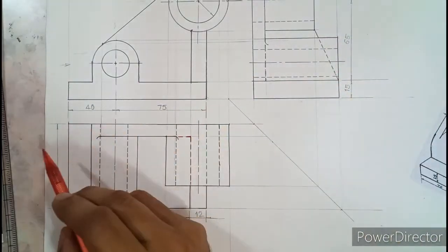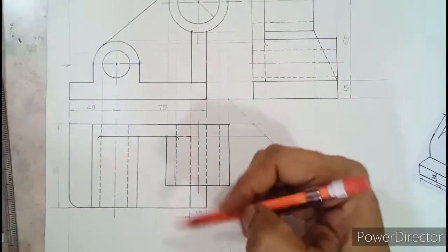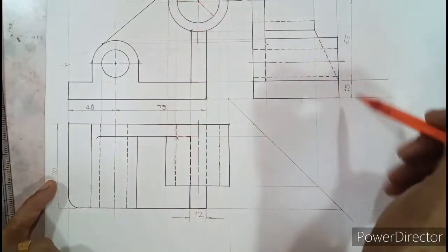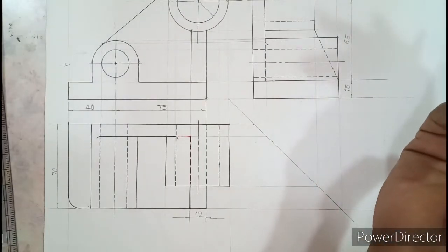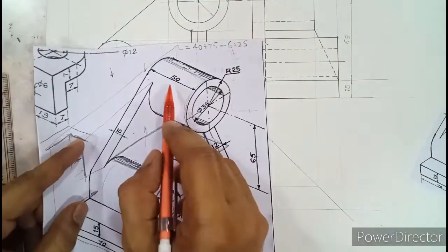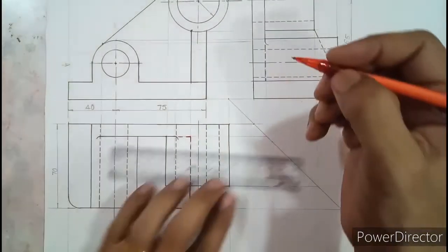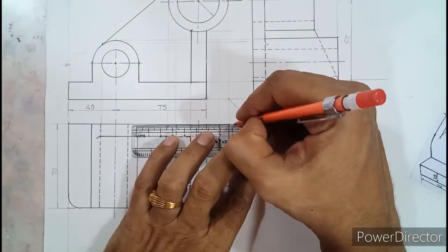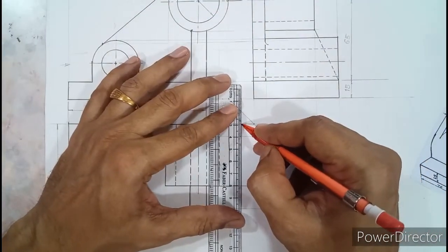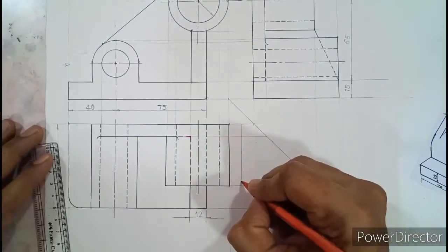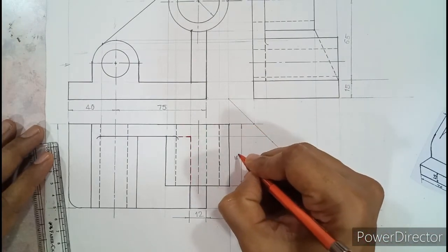Let us count the dimensions. 1, 2, 3, 4, 5, 6, 7, 8. So we have shown 8. We have to show 2 more. Okay. So this 50 mm can be shown in the top view. So let us show 50 here. We can draw a medium dark extension line, and we can show 50 here. Instead of 50, if someone else wants to show any other dimension, it can be shown. I think linear dimension is easy to show.